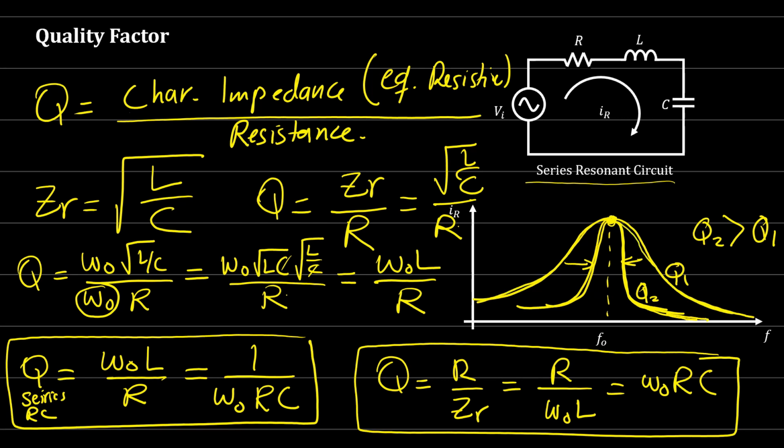Now, this quality factor issue: when we increase the quality factor, this can significantly improve the behavior of the filter within the resonant converter. Let's say, for example, you want to apply a very significant filter to allow a band of frequency to pass and reject other frequencies. So what you need to do is increase the quality factor. If you decrease the quality factor, then your filter will not reject the higher or the lower frequencies effectively. Now, this is when the input voltage is only a sine wave.